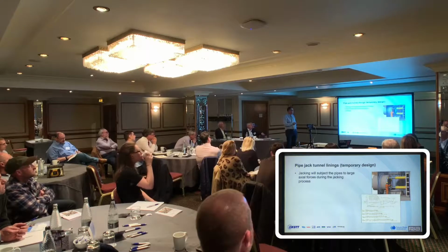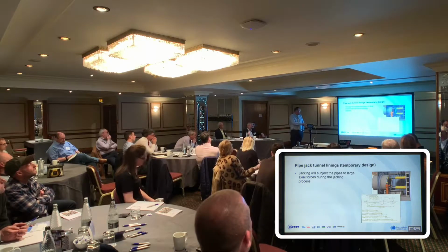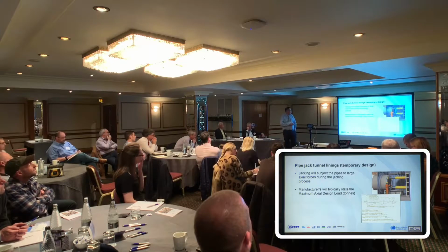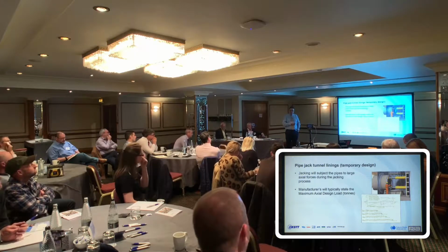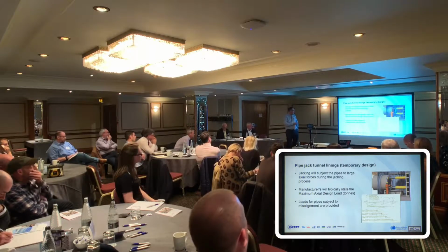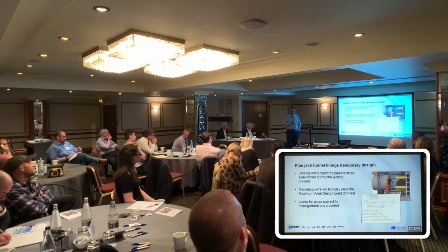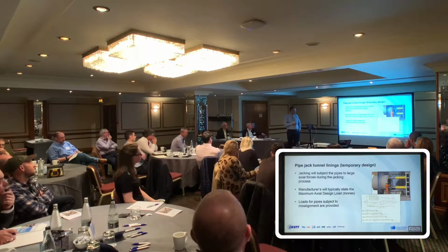The jacking pipes are subject to large axial forces, or can be, during the jacking process. That's just a shot of them. That's the main jacks in the pit. The manufacturers will typically give you maximum design loads that you can push through the pipes, with an appropriate factor of safety. They'll also tend to give you a steer on what those loads are if you get any misalignment along the pipeline.